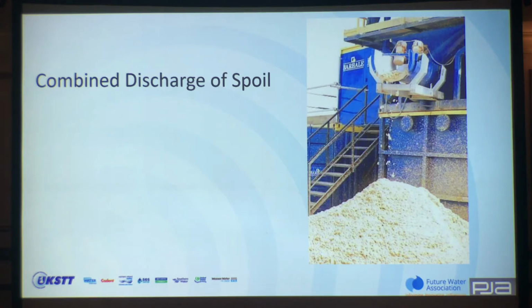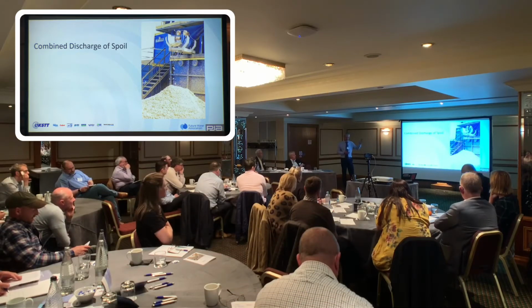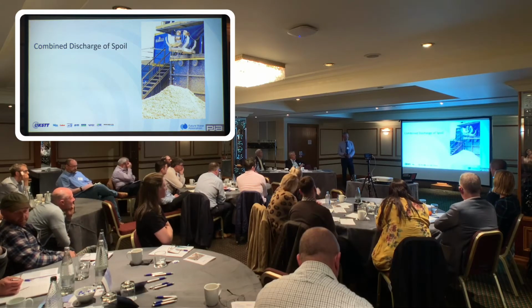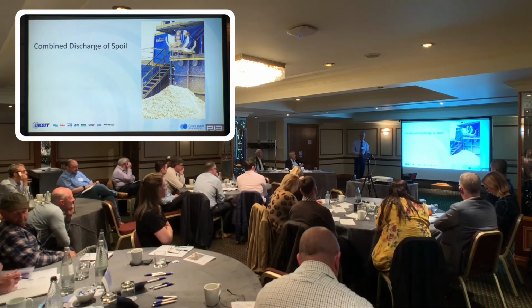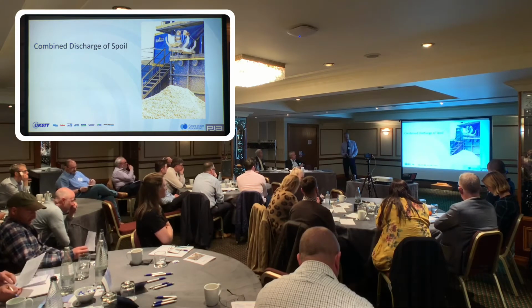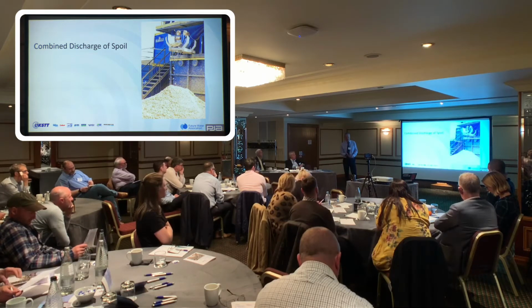So in terms of the design of a slurry, if you consider that the separation plant is there to take solids out of the slurry, it's fair to say that in most circumstances, other than in granular soils or difficult situations, you would be wanting to just use water. A, it's cheap, and B, it has a very good cleaning capacity.